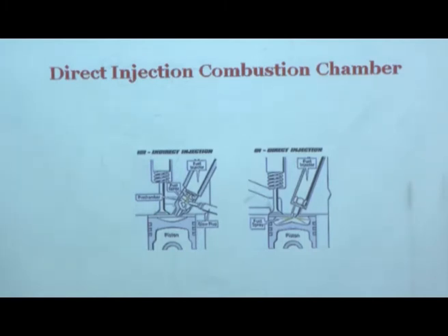So when you do the compression, that much heat is not lost from the compressed air, and it does not cool down to very low temperatures, and as a result you are able to start the engine without much difficulty. And that is why every IDI engine is equipped with glow plug. You will not see this in DI engines.